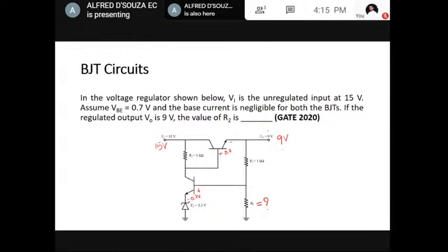It's very easy to solve. First check the output side. We have voltage, two resistors, and in between there is a tap. So it's a simple voltage divider. If you know this voltage, I'll mark it as VA. You can relate V0, R1, R2 and VA using the simple voltage divider rule. So VA is V0 into R2 by R1 plus R2. You know V0, you know R1, and you are supposed to calculate R2. For that, you should somehow calculate how much is VA.